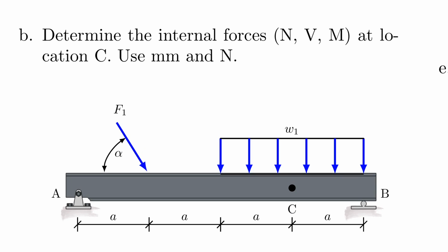So for problem B, it's very similar, except now you're actually dealing with distributed forces on top of that. And please don't get too confused about that. I see that sometimes in the classroom that students initially get confused, but all you have to do is cut through that force as well. So you either release the entire right system or the entire left system, and one of them might be easier for you than the other one, but I'm sure you can figure that out yourself.